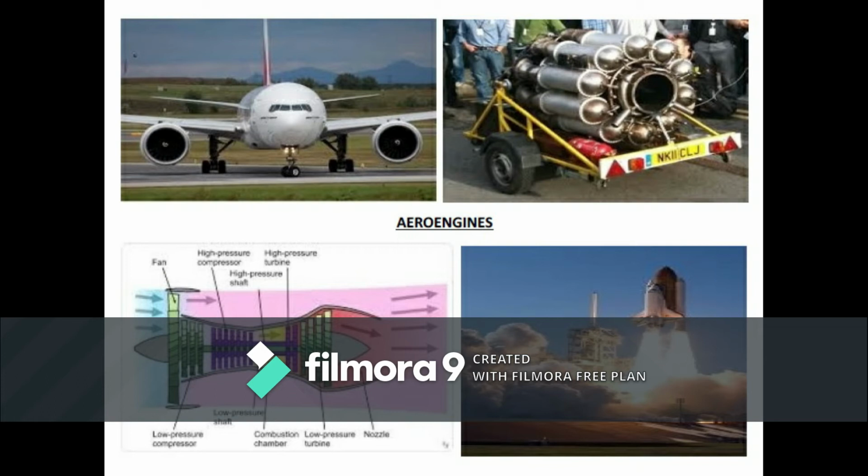That's all. The only demerit is that this type of engine, ramjet and scramjet, cannot work at low speed. When the aircraft is static on the ground, it will not work. It needs supersonic speed of air to enter the air intake.